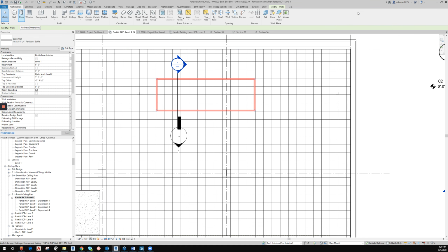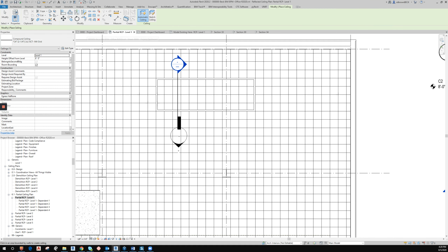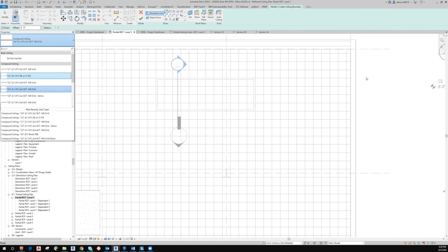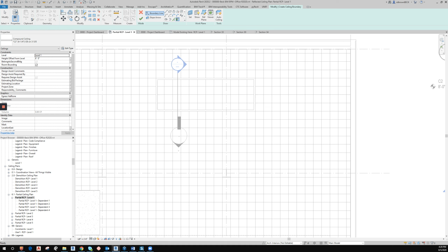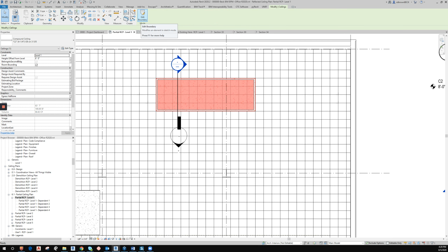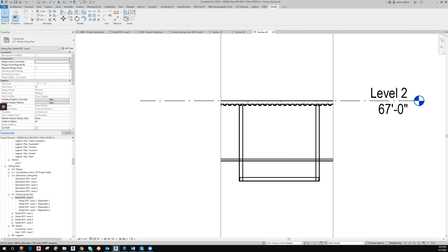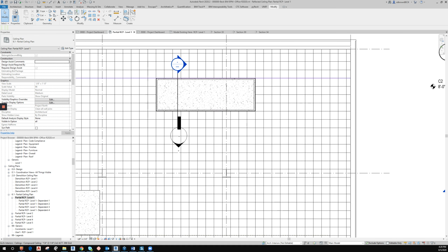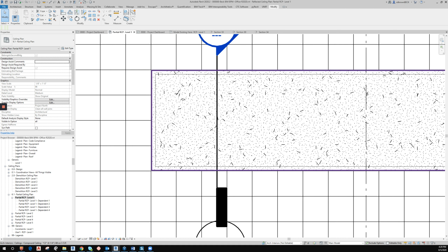Okay, now you're ready to create your ceiling. And the key to creating this ceiling is using the sketch tool, select your gypsum board, and use the pick wall tool and check this box, extend into core. That's critical. And now we're going to tab select on our ceiling. You can check your ceiling height and finish sketch. And now you'll see that your ceiling's been created. And if we look at this in section, you'll see there's an overlap there. And if we see that in plan, you also see that overlap. So the next step is to use the join geometry tool.